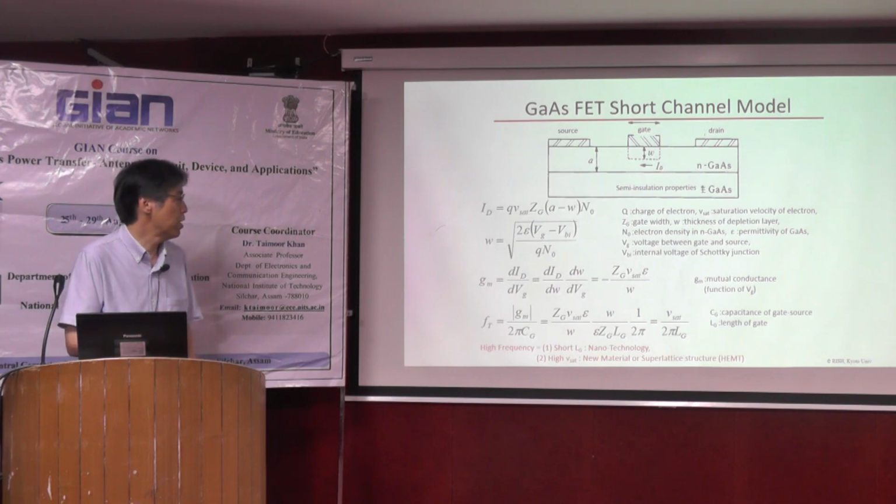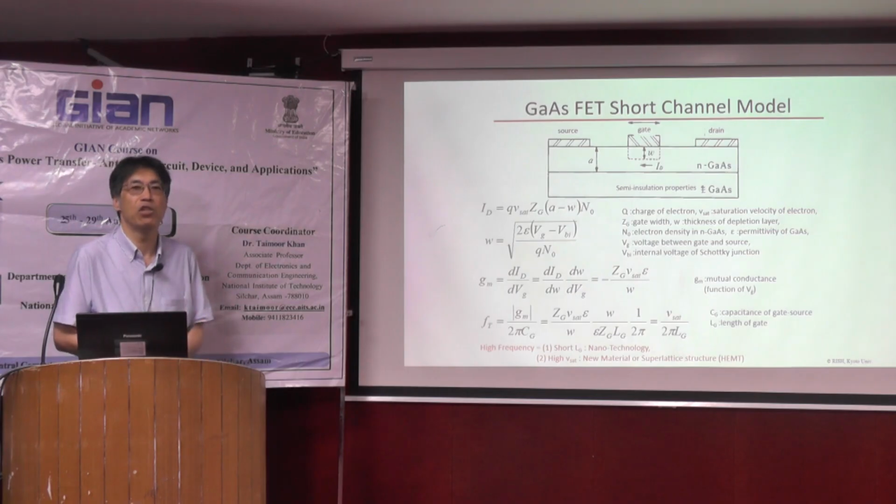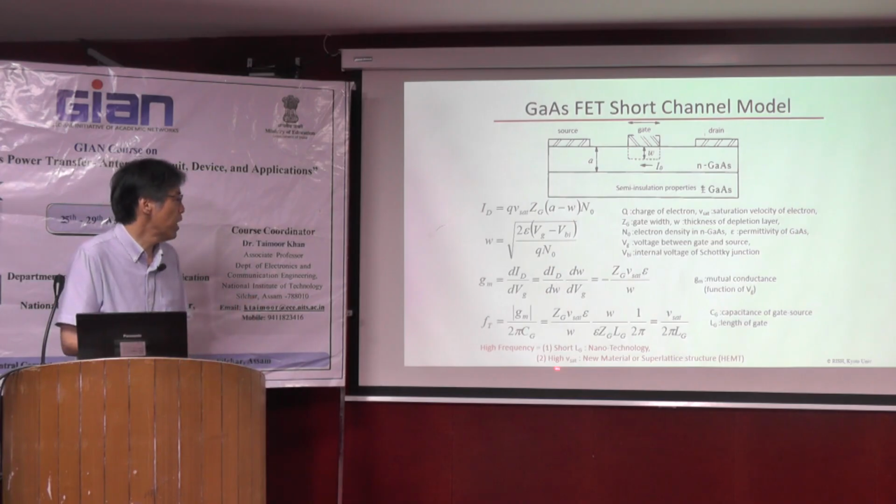On silicon, we can now apply higher frequency by developing very short gate transistors. So this is a simple reason to increase the frequency on silicon, and the frequency will also increase on silicon carbide, etc. And additionally, if we can develop a higher saturation velocity, we can increase the corresponding frequency.